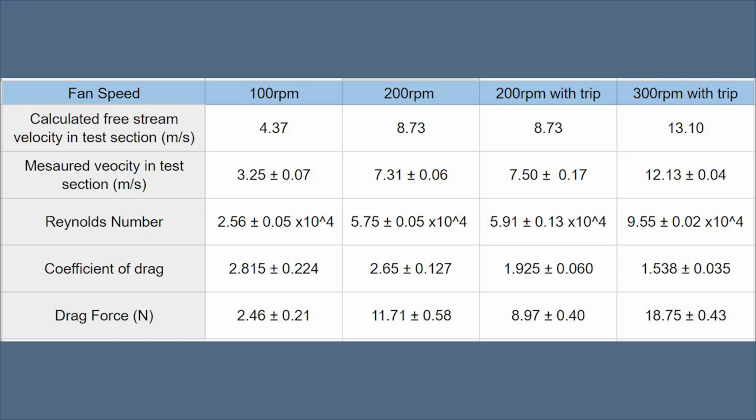It can be seen in the tripped flow that the turbulent boundary layer also had the effect of delaying flow separation, reducing drag on the cylinder. This is important as it would affect propellant efficiency in the case of an airplane, or increase stresses on any circular cylindrical structures within a flow.